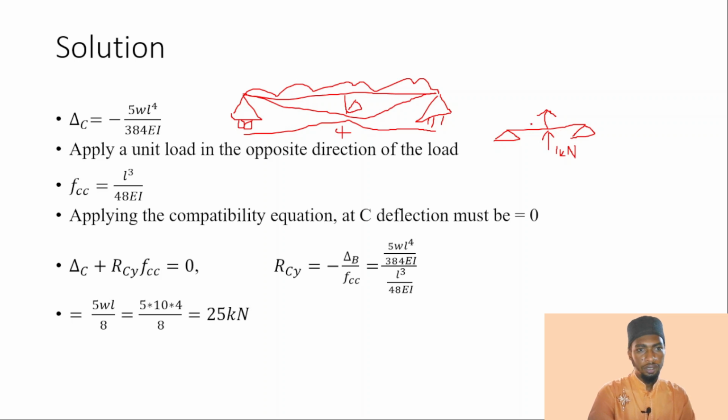You see, so it's just the direction of the point load going upward instead of downward that we are familiar with. Okay, so what is the formula for this? The deflection of a simply supported beam carrying a point load at the center is given by WL cubed over 48 EI, and since the direction is upward now, the deflection we leave as positive.